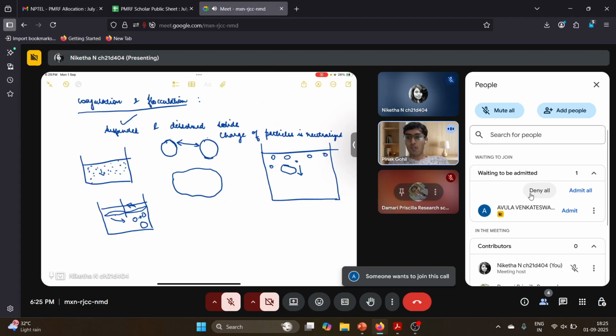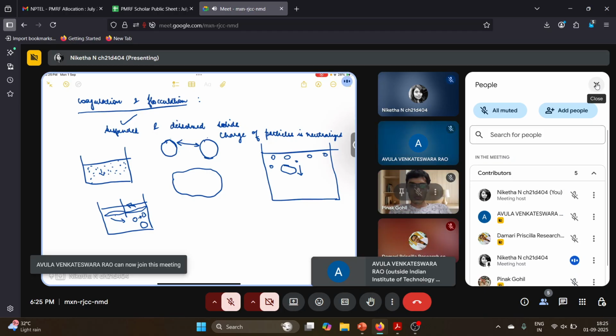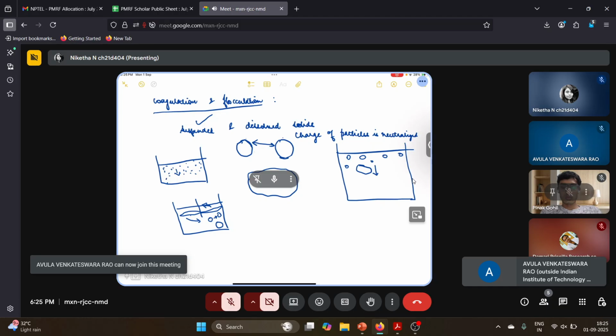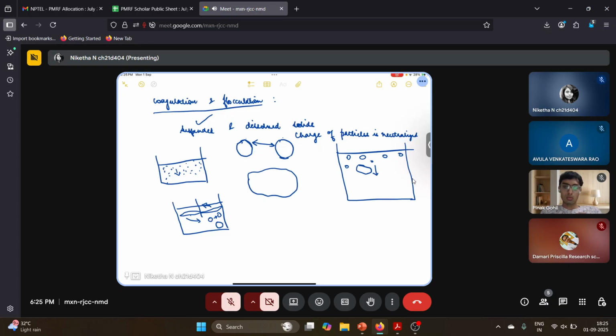It means just like a clarifier. See, clarifier, yeah, something like that. In a clarifier as well, the turbine rotates slowly. In the clarifier, we have a skimmer on top. So that will remove all the oils and stuff. So this is just for giving a gentle mix so that the flock can form.